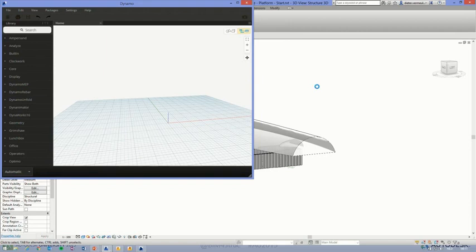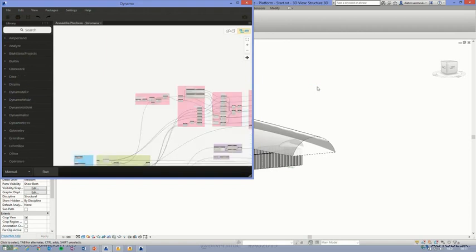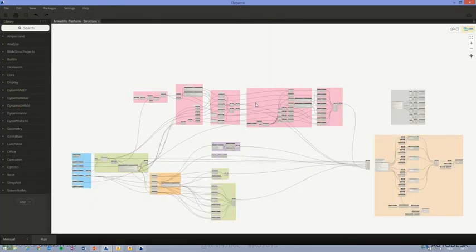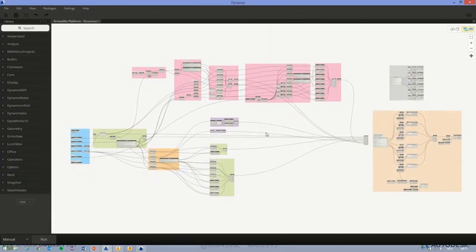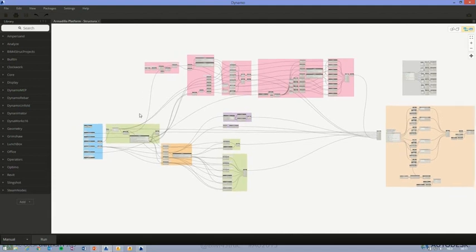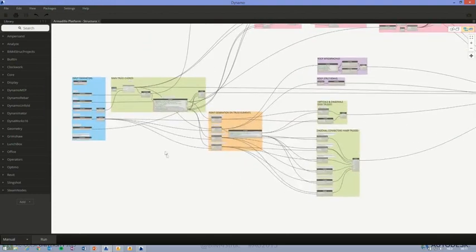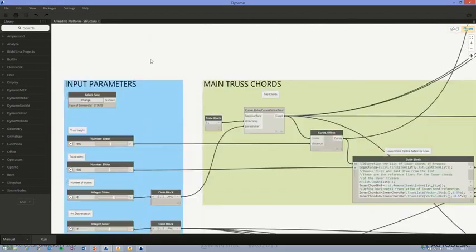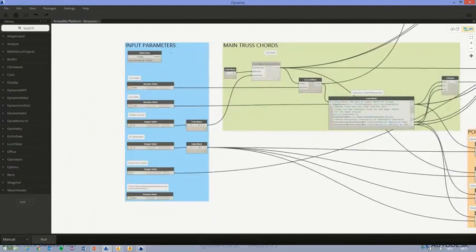Now, this will be the specific workflow that can be followed. First we are going to start with the structural model. Then I will make a structural analysis of that model using Dynamo again. Do some manual optimization, which means we are going to take one of these trusses and perform some manual operations to get a bunch of results out of it. And then we are going to touch on genetic optimization, so let the computer decide which kind of truss would be the ideal one for my solution.